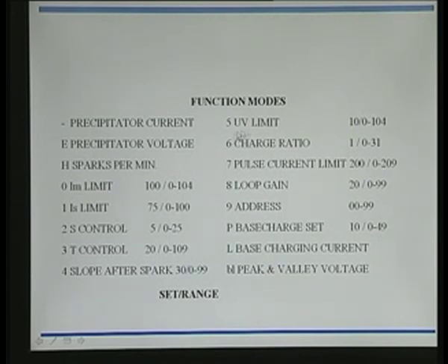UV is not ultraviolet, it is under voltage, we have already seen. So that also you can set here. Normally 10 is set here, and up to 40 also can be set.